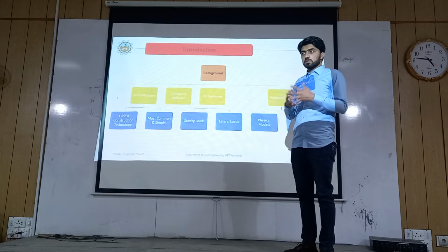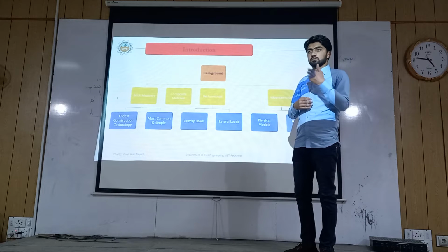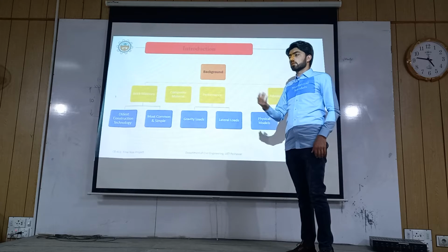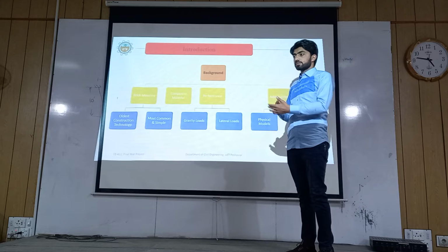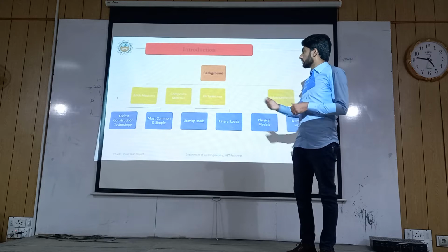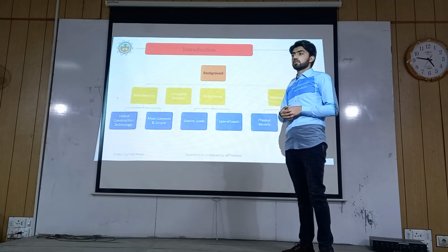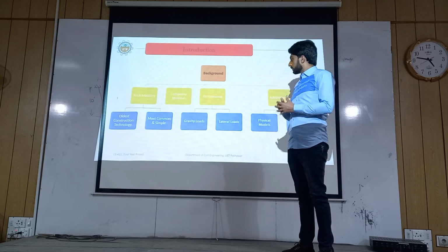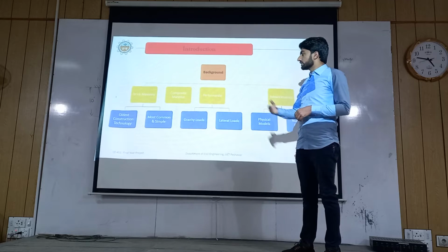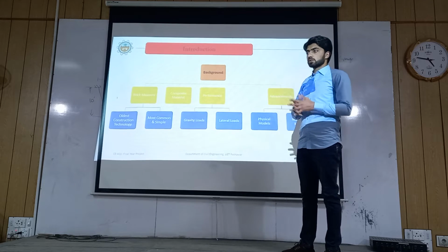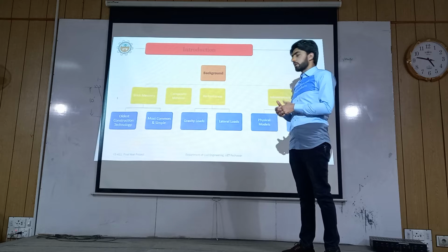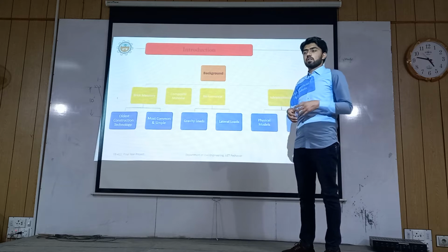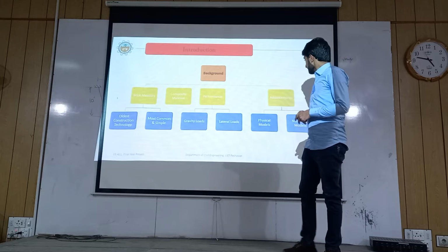Masonry is a composite material. The composite nature is due to the materials that we use in brick masonry, like masonry blocks, bricks, and stones also, and the other material is the cohesive material, which is mortar. The performance of brick masonry is very good when it is subjected to gravity loads, as it is used as a load carrying mechanism, and when it is subjected to inclined lateral loads, it shows poor results.